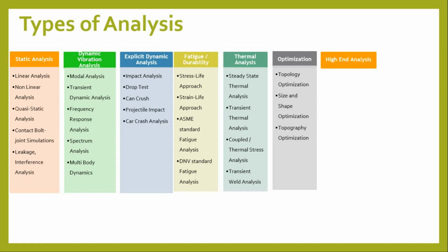Then there are high-end analyses. We know that mold flow analysis and multi-physics analysis are there, like fluid structure interactions. When any CFD-based analysis, CFD plus FEA analysis, comes into the picture, that is nothing but your high-end analysis. Take an example of a pressure vessel under transport loading conditions, when it is loaded on a vehicle. If liquids are there, due to sloshing there will be some vibration, and due to these vibrations or sloshing loads, stresses are developed. That comes under fluid structure interactions, right? So multi-physics are there.